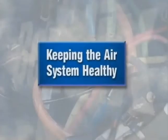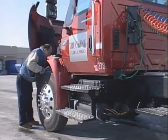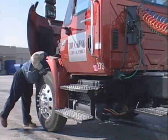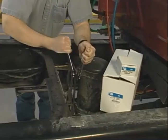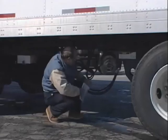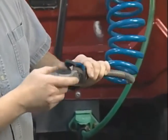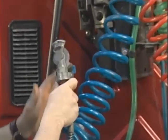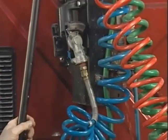As our final topic, we'll talk about ways to improve overall air brake system health. The number one way, pay attention to anything that impacts the quality of air in the system. That includes regularly scheduled reservoir drains and air dryer cartridge replacements, regular pre-trip inspections. And be aware that open glad hands are an easy way for contaminants to enter the system. When it's not being used, close the coupling.